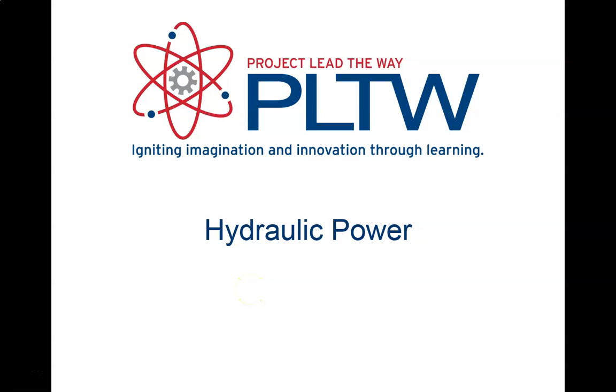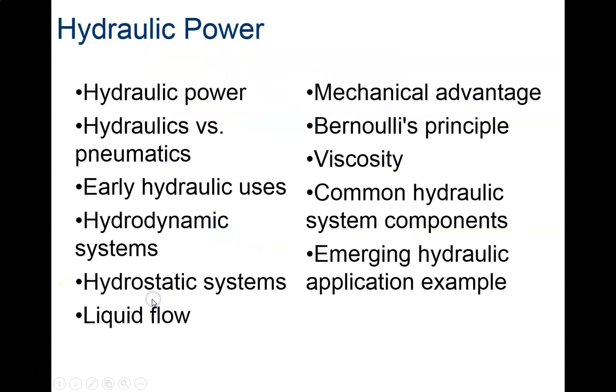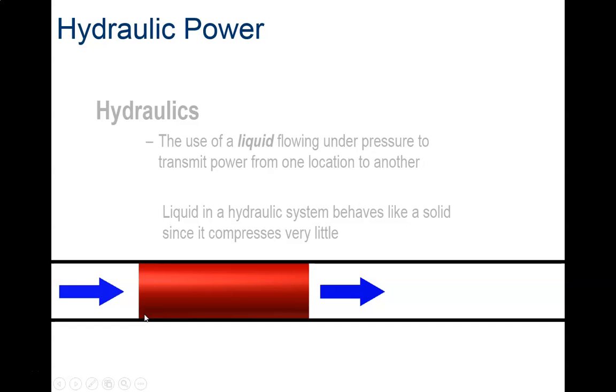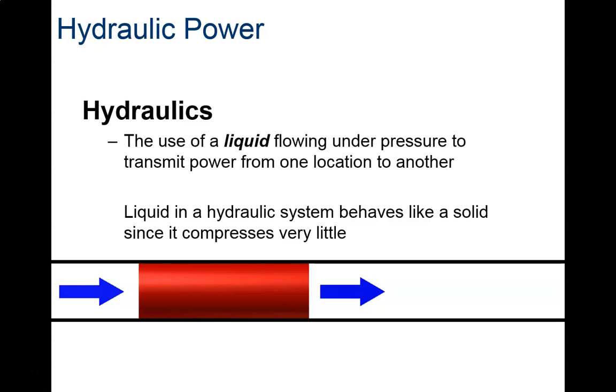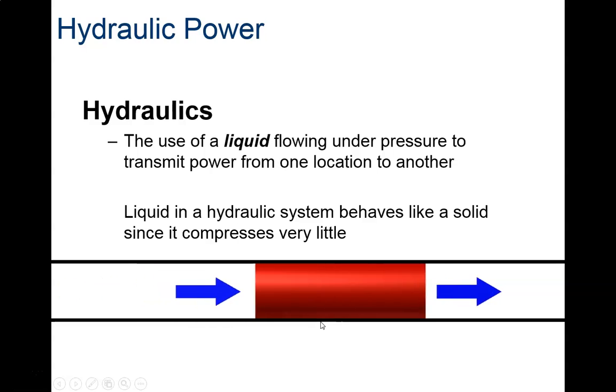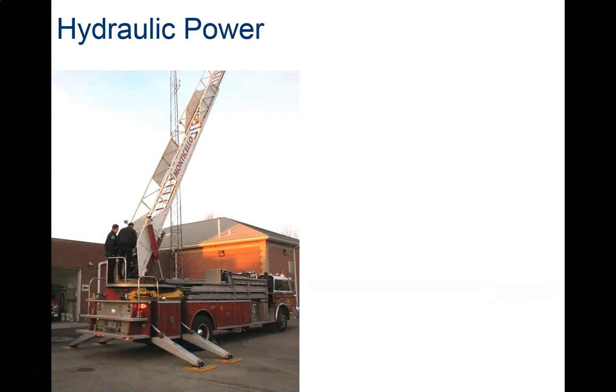The other piece of the puzzle here with fluid power is hydraulic power. And hydraulic power uses a liquid. Typically it's an oil of some sort. And the liquids are not compressible. So when you push one end a little bit, something moves down on the other end a little bit, assuming it can, otherwise the pressure just builds up. So when you push something, something else moves.